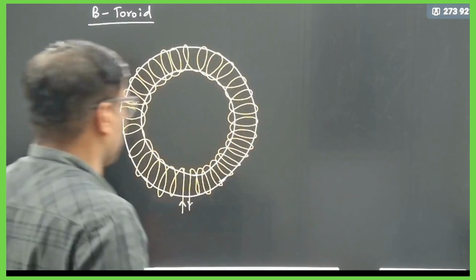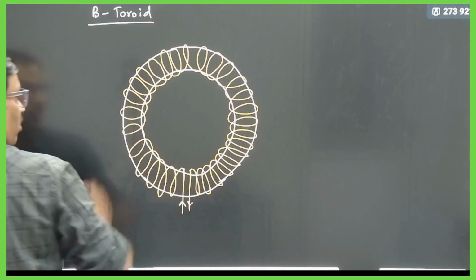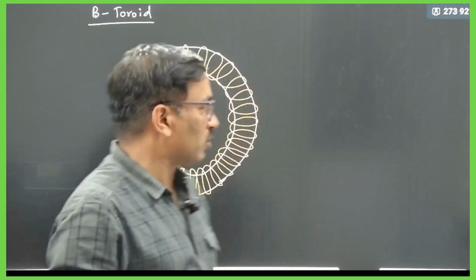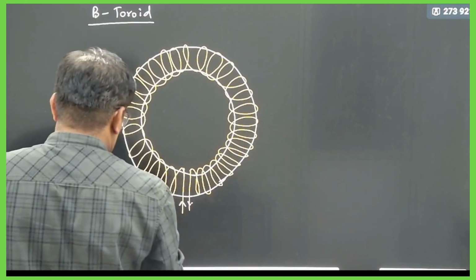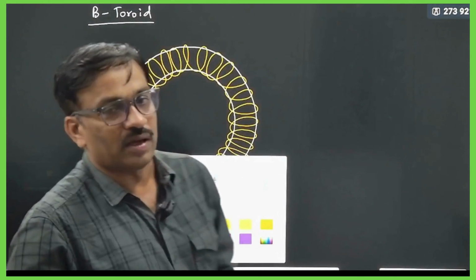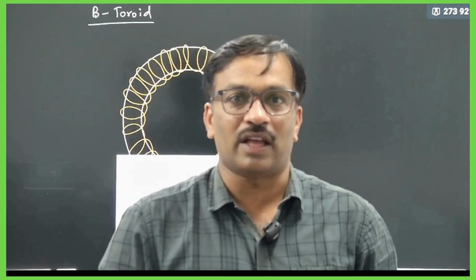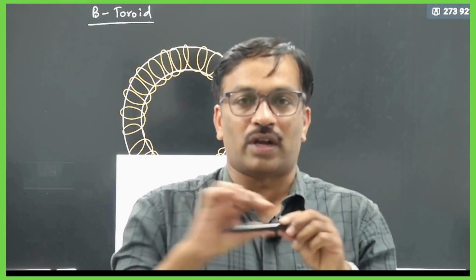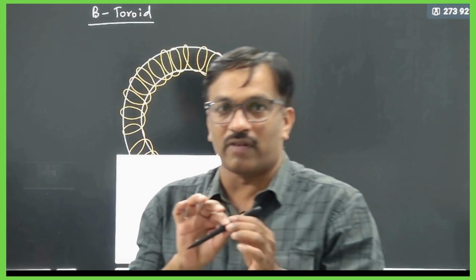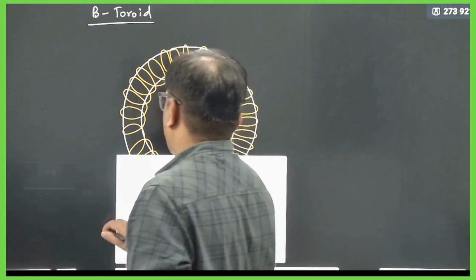So be careful. If contact is there, instead of flowing through the coil, the current will flow directly, and at that point the magnetic field will not be proper. This is very, very important. That's why in our motors, the copper wire has an enamel coating, so that even if there is contact, the small enamel layer on the wire will not create conductivity.